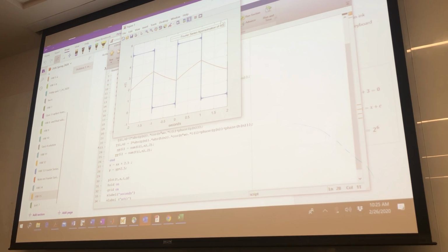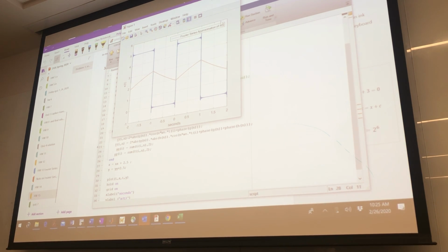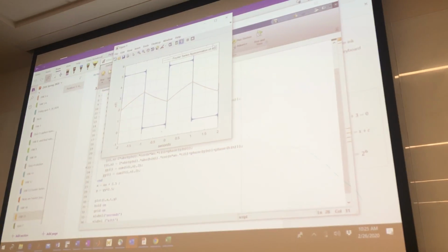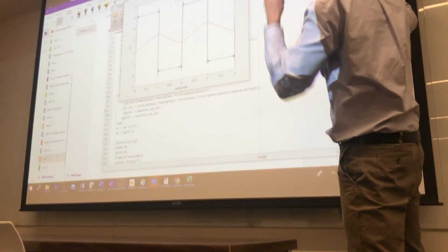And so what happens is, to get the initial value right after it transitions, take this out. Well, what would the voltage be here? It would be simply that current, right, times this resistance. If it's at a high state, it would be 5, wouldn't it? So take a look. Well, it should be 5.